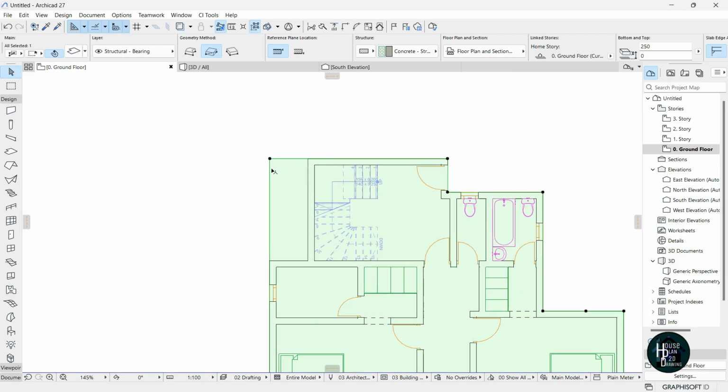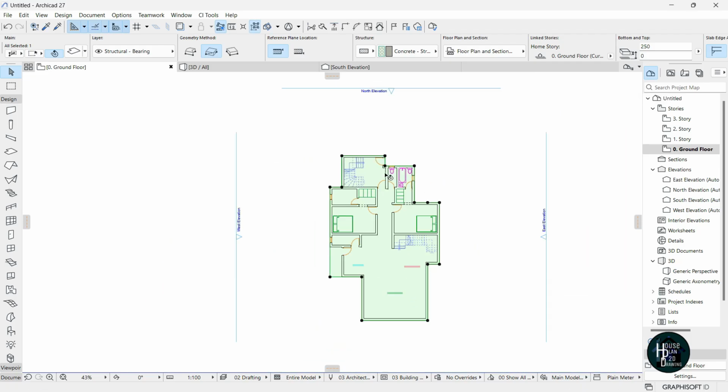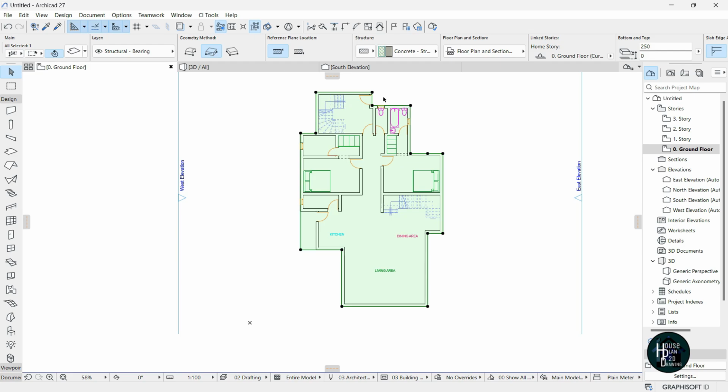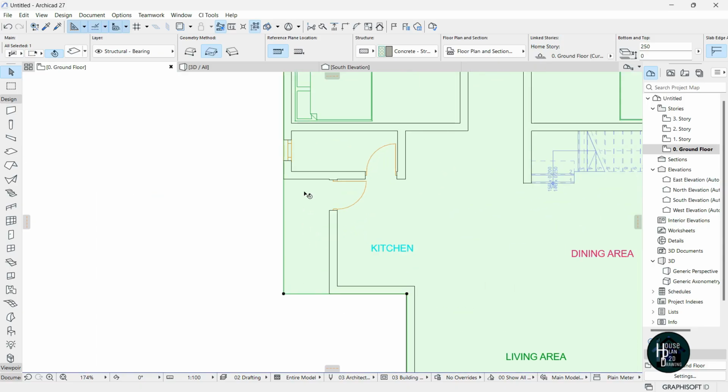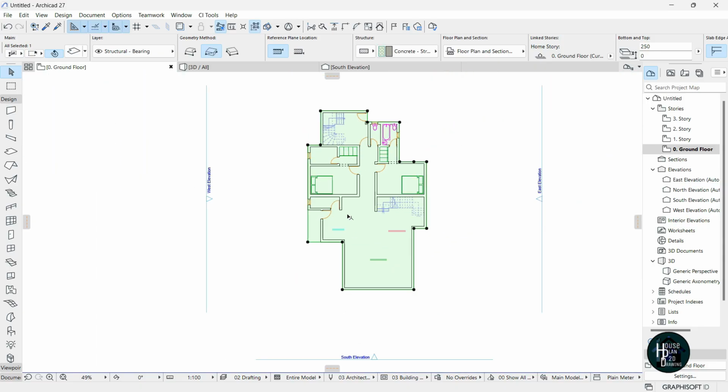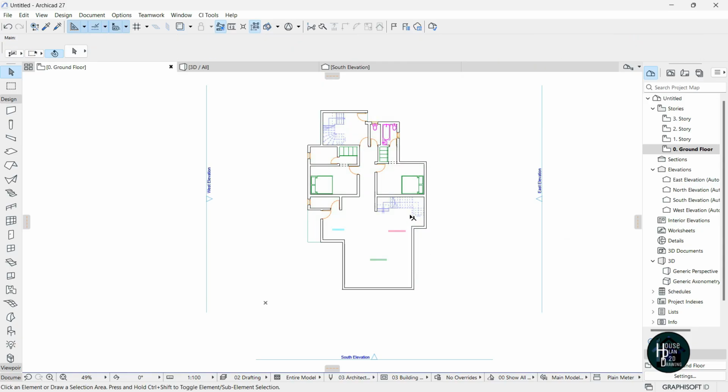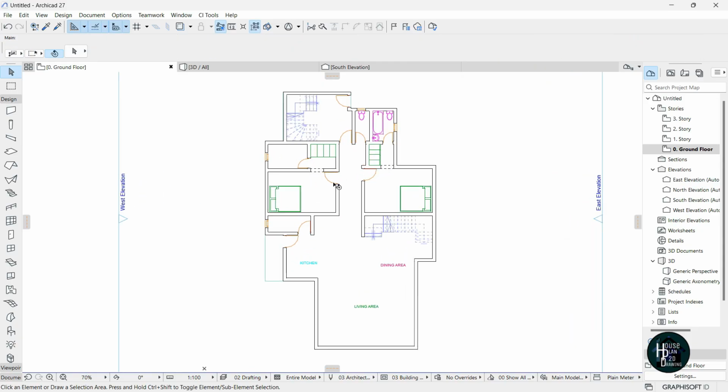Now this one is back to normal, so you want to click this again and make sure you're selecting this subtract from polygon and just click, then click this side. Now you're going to have that cut off. As you can see, the slab itself conforms with the building. We want the side to be left like this, so this side can be the veranda for the kitchen. So I'm going to press escape on my keyboard and now we're going to go to the 3D section.